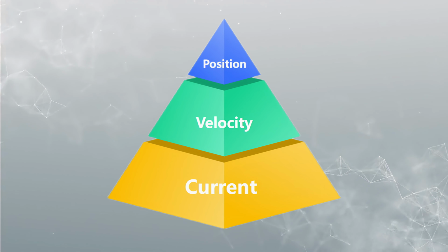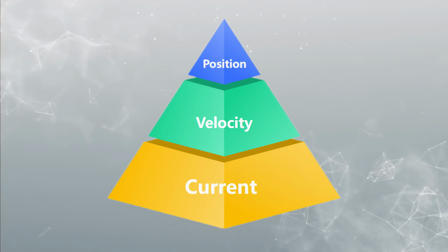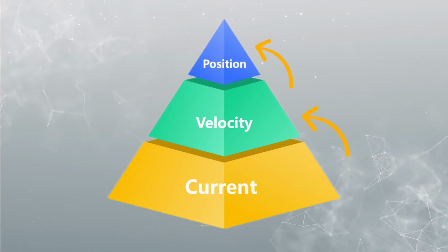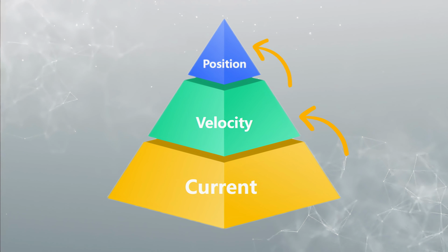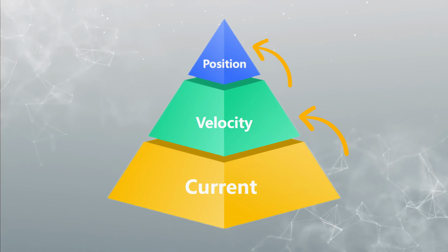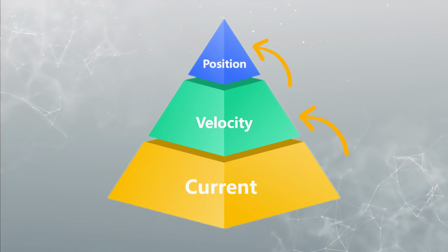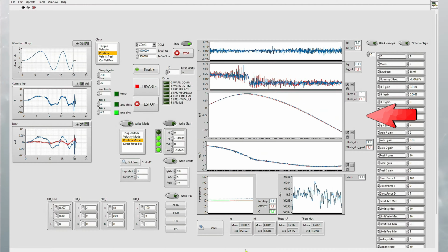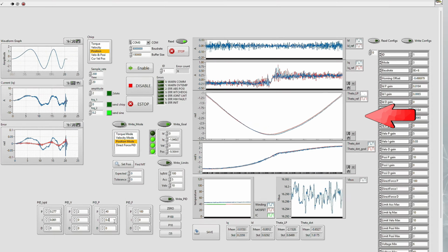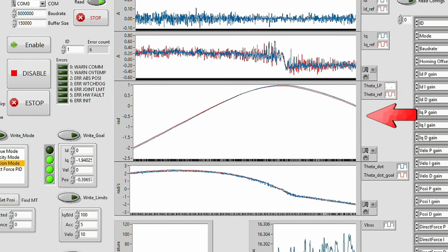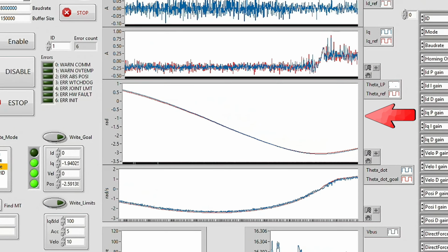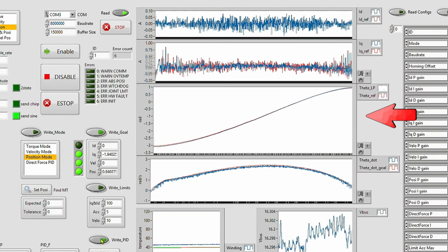Next up is the core focus, Mode 2, Position Mode. This operation engages a classic 3-loop cascade architecture nested as position over velocity over current. The tuning metric for this layer is straightforward. The present position should closely trace the goal position with a fast rise time while minimizing transient overshoot as much as your mechanical system allows.